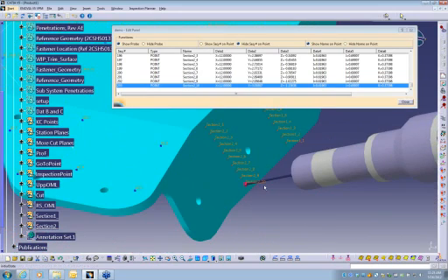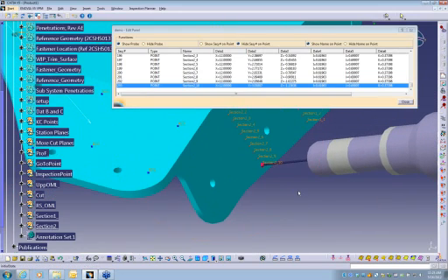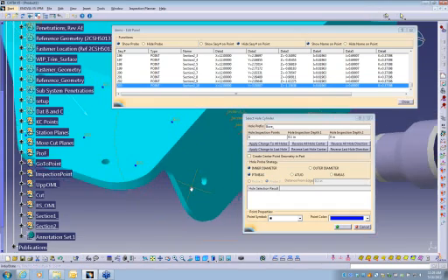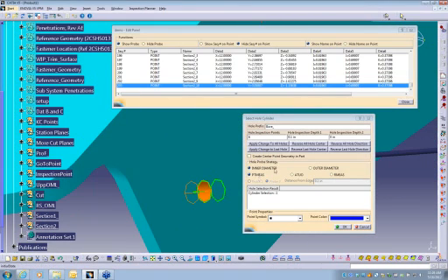Again, if you're right here, these are 5-axis holes. I already have my probe angle set, and I have my 1/4 inch. This time I need to do this 5-axis hole. Let's say that I wanted to, we'll call that bore is fine. We want to go into it 100 thousandths. Same philosophy. I come in here, I just pick the inside wall.